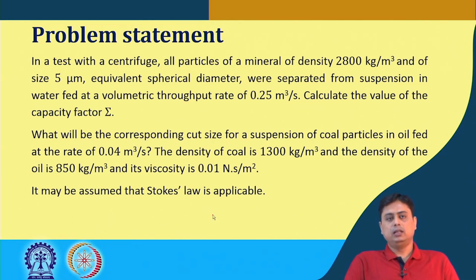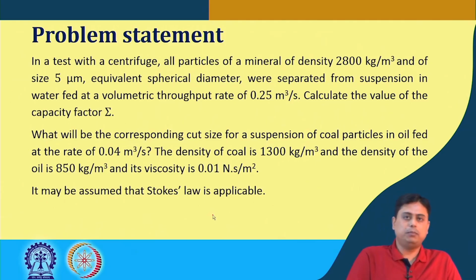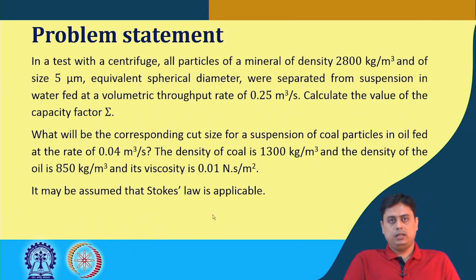And the second part is, what would be the corresponding cut size for a suspension of coal particles in oil fed at the rate of 0.04 meter cube per second. The density of coal is given, the density of oil is given, and viscosity is also provided. It can be assumed that Stokes law is applicable.